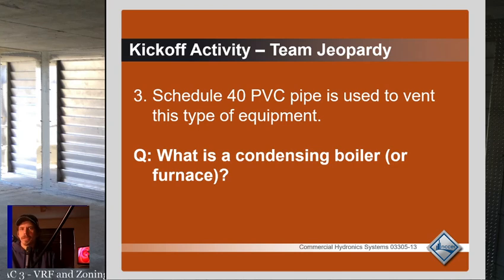Your glue joints start to leak because the glue starts to break down and all that nice neat stuff. So usually what I say you should really think about is, if you're running a commercial boiler system where you're going to have water temperatures that get close to 180 degrees, then I would probably recommend polypropylene plastic or stainless steel vent. If you're running less than that, if you're running 140, 160 degree boiler systems, or even better, 120 degree radiant heat systems or something, then PVC is fine all day long.